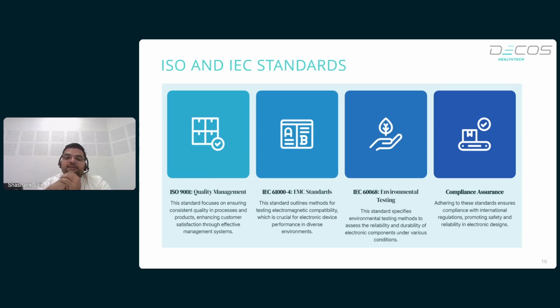For example, IEC 60068-2-14 covers thermal shock, rapid temperature change, and thermal cycling for electrical and electronic products. Similarly, IEC 60068-2-27 describes the standard process for testing mechanical shock resistance. What is the amount of shock which the product has to undergo? What is the sine wave? Even the sine wave is defined, that this is the sine wave which the product has to undergo when it is clamped on the vibration table, right? In order to pass the test, or in order to ensure compliance with the standard.